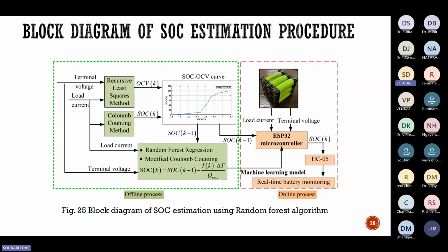From that OCV and SOC data, we can get the SOC OCV curve, and using the load current and terminal voltage, we can train a model to enhance the SOC estimation. Here we have used the Coulomb counting method for that modeling.